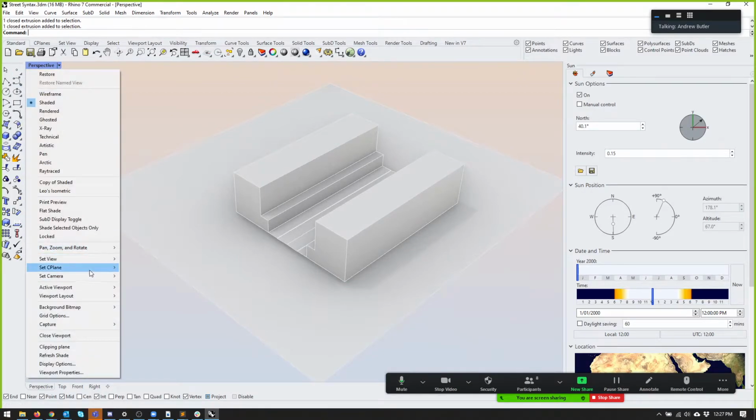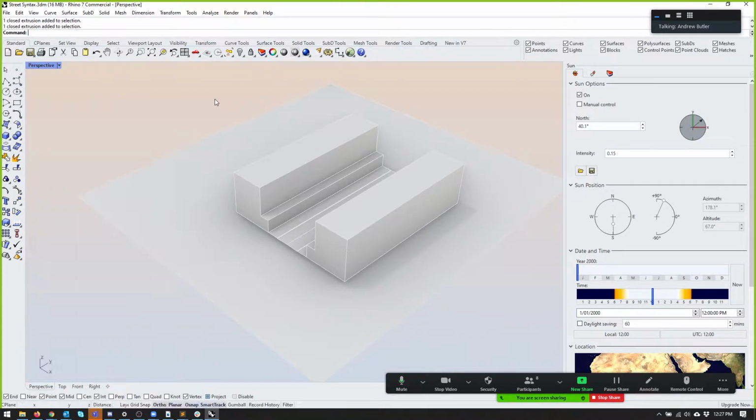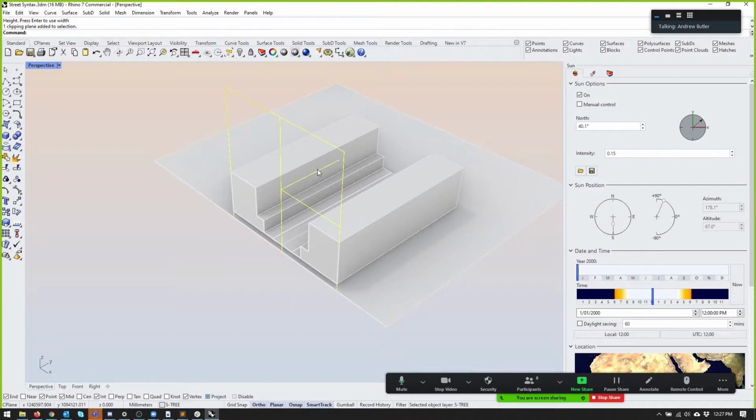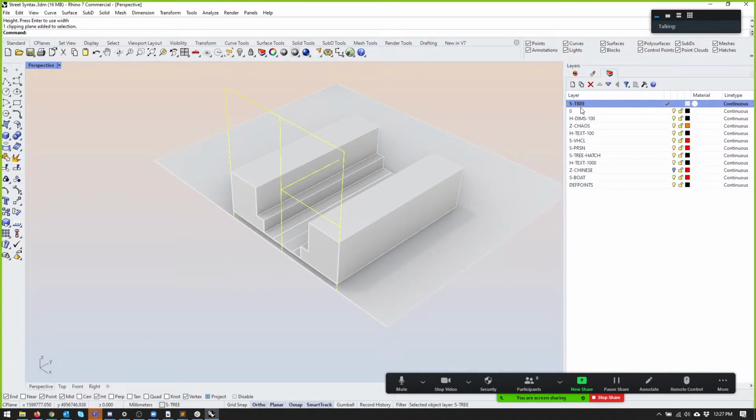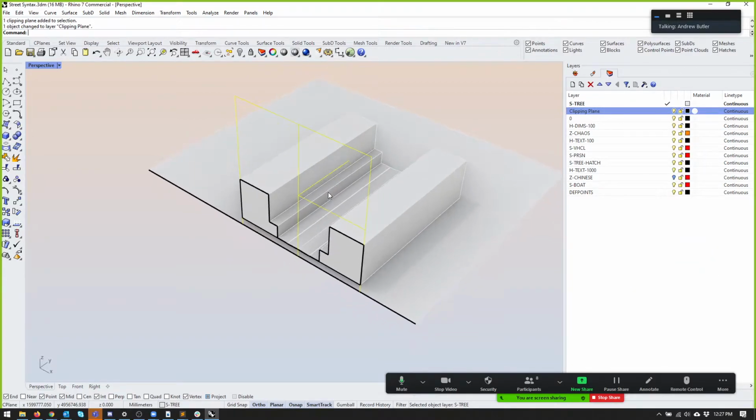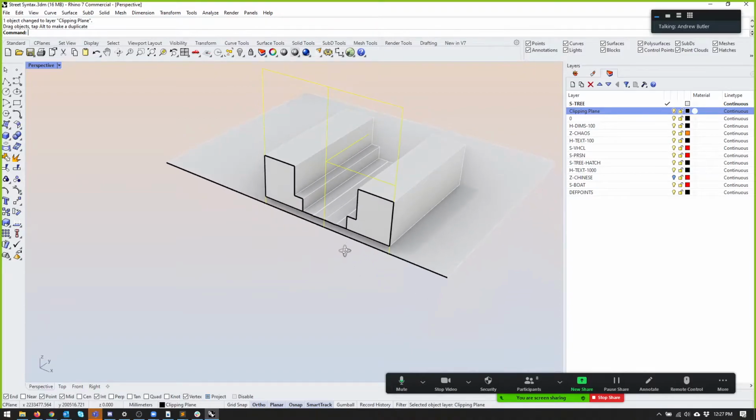Well, if you use a clipping plane. Yep. That'll give you automatic. So clipping plane. Has everyone used clipping planes yet or not? Yeah. From the architecture policy. And Leo, if you put that clipping plane on a black layer instead of a white one. Because Rhino's a CAD package, they use layers.